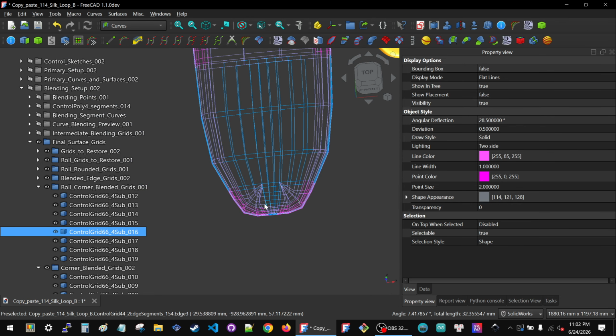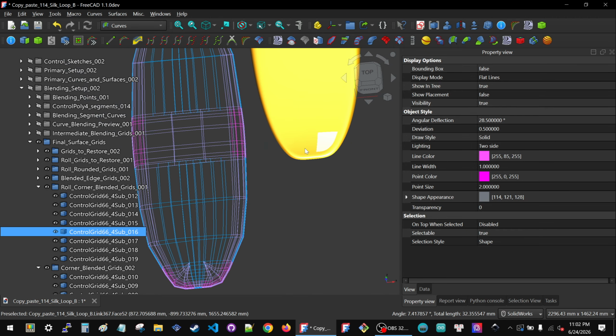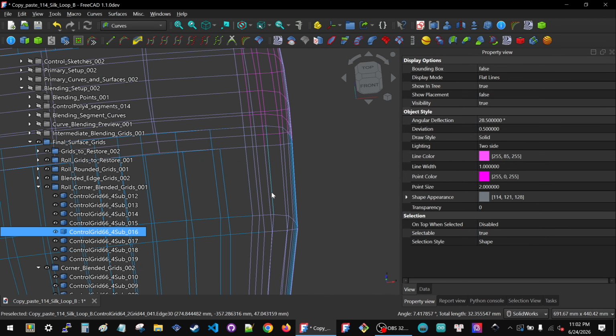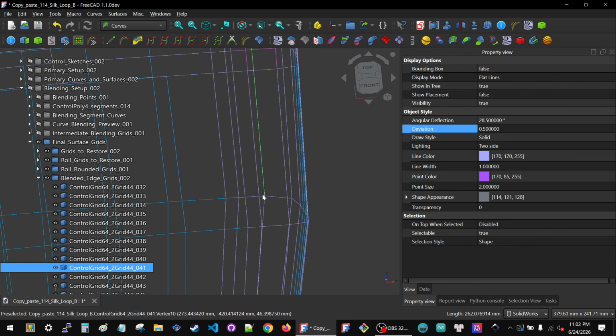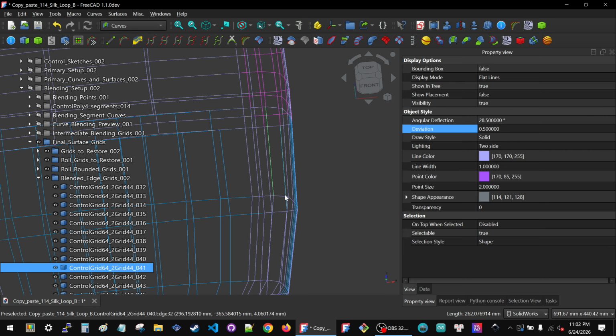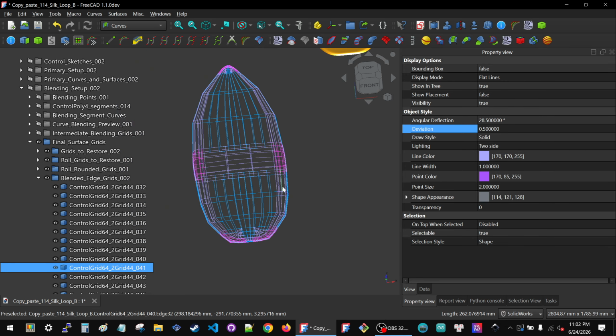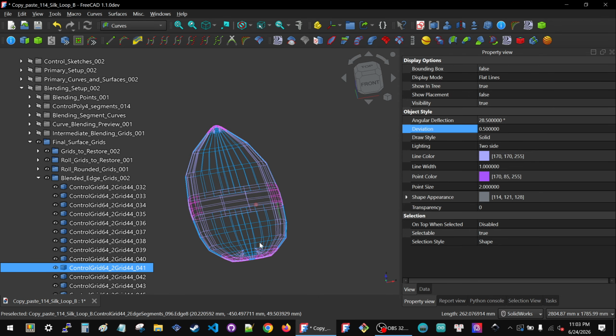But most of the time, the effect is negligible, and so you should really focus on making your primary curves and your primary surfaces better, and placing your blends and placing your cutting points better. But one of the things you can do with those, by adjusting these blends, is you can, by tucking the points back towards the corner, you can create the impression of a smaller blend by pinching that blend. And so you can obtain the illusion of a sharp corner even when you have a very large blend. So that can be useful in some cases.